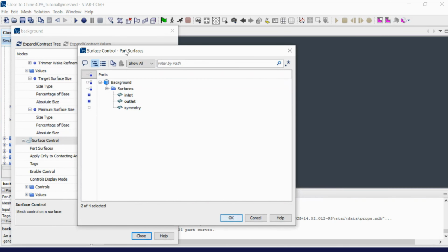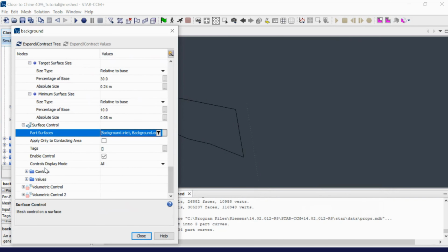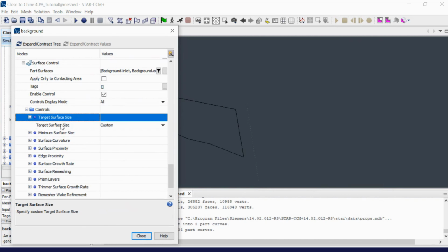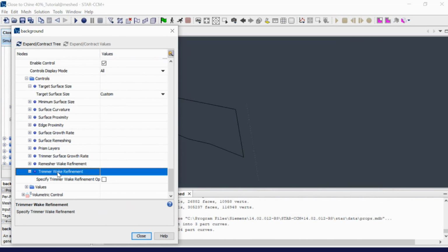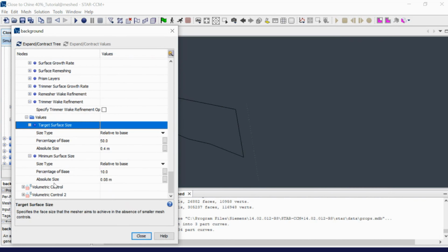To include the prism layers, the extent of the volumetric control must exceed the boundary. The trimmer refines with either an isotropic or anisotropic cell size. If you specify by option, the smallest cell size in each coordinate direction takes priority.